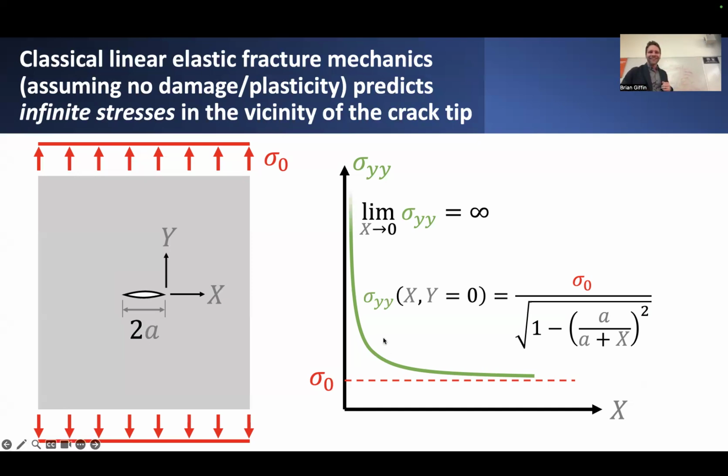But the problem is, theoretically, assuming linear elastic material behavior anyways, which is not quite correct, but assuming you did use this approach, it says that the stress is just going to go to infinity. And what's worse is if you said, okay, well, I just need a finer mesh, I'll just use more elements, I'll refine it even more. You'll never converge because you're trying to converge to an infinite value. So this is really the troubling thing about trying to define a stress-based failure criterion for fracture. It's really not feasible if you're assuming linear elastic fracture mechanics.